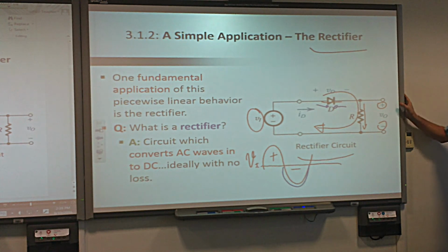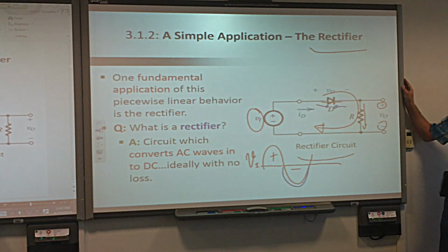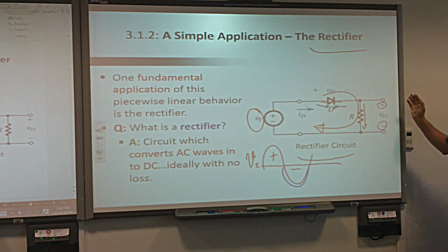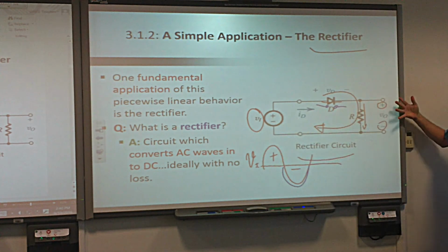Very good. So after we finish this cycle, another cycle will come, yes or no? So output voltage, was it negative or can it be negative? No. Cannot be negative. See? So we have taken an input that can be positive and negative, and we got an output that is always 0 at the minimum, but normally it can be positive. So it's always above or equal to 0.